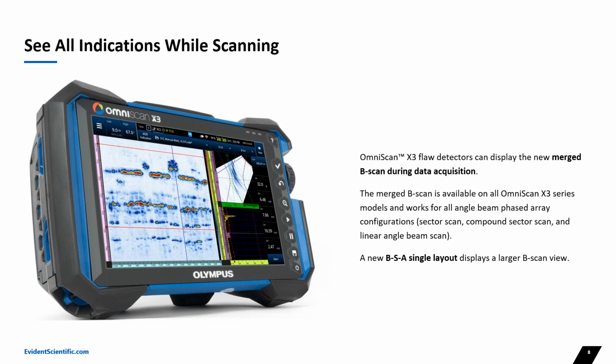Another benefit, of course, because it's on board the OmniScan X3, is that it's available live as you scan. So if you have a weld configuration where the merge B-scan is really helpful, you can display it on the instrument as you scan. This is especially handy for manual scanning.